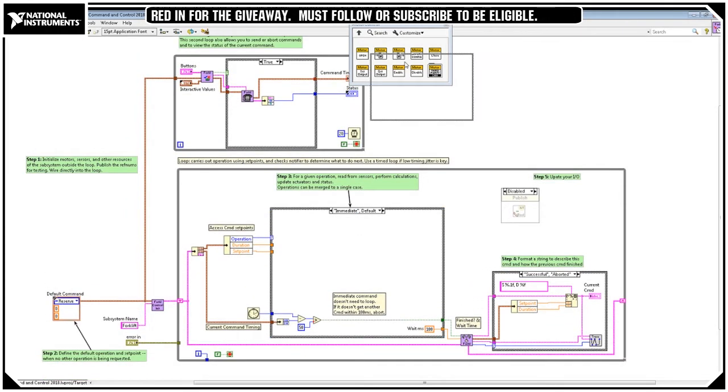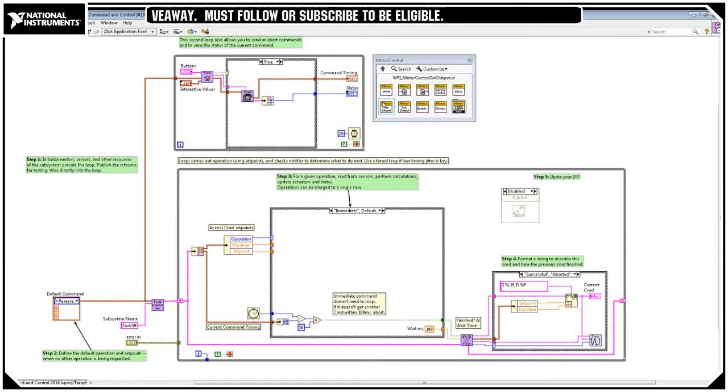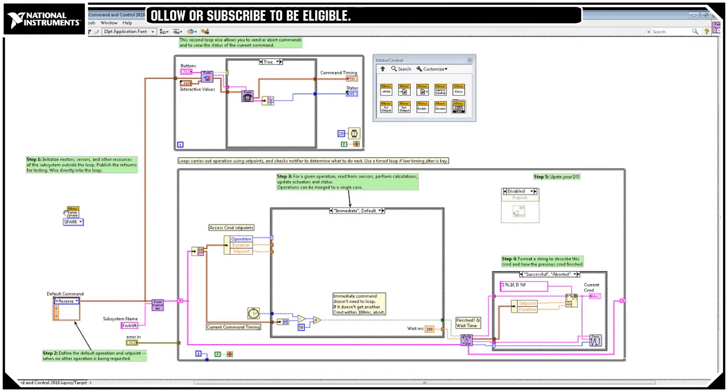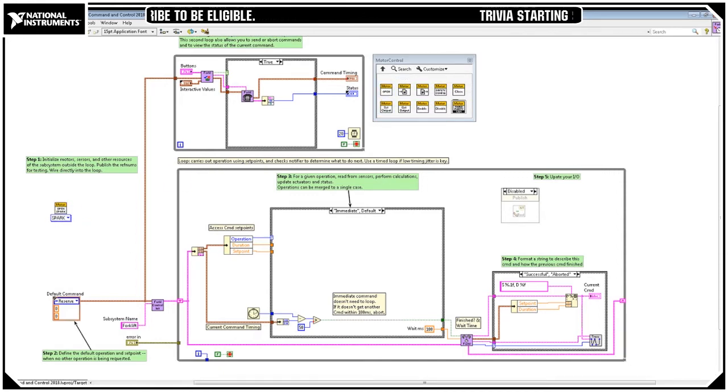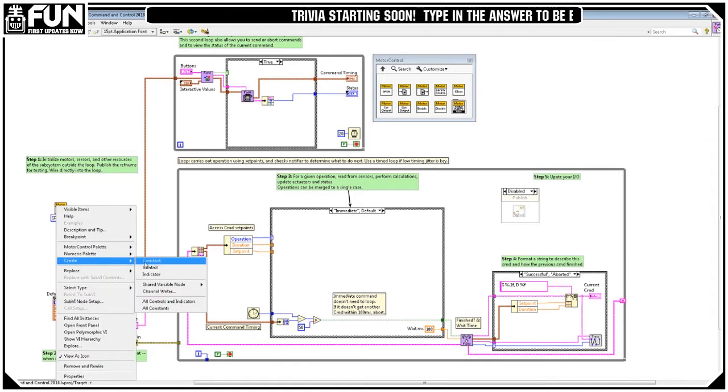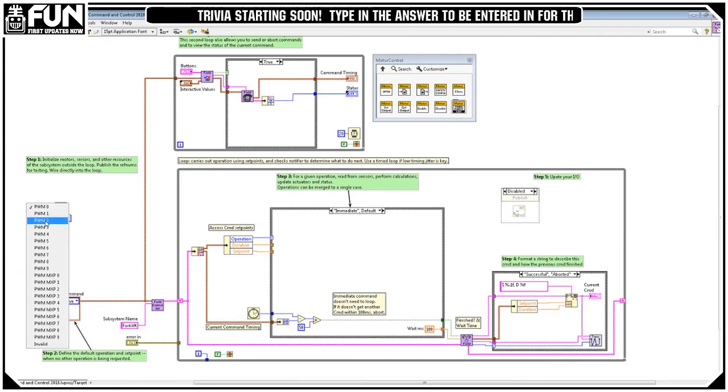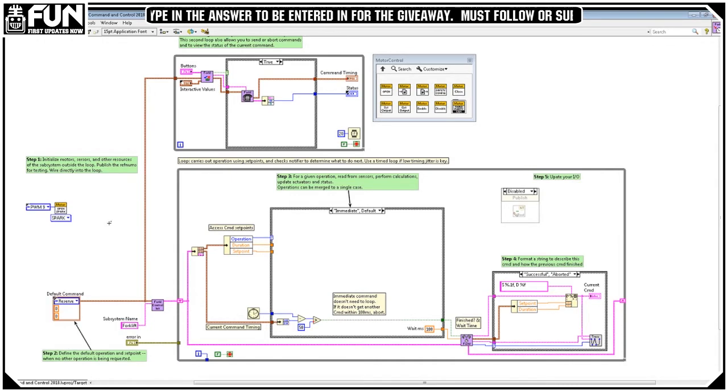You can see I have our motor control palette already open over here. I'm going to open up a new motor. Sure, it uses a Spark controller. Right click and create a constant. We'll say this is on PWM 9. My drivetrain is on 0 through 3, so we'll put this down on PWM 9 away from those.